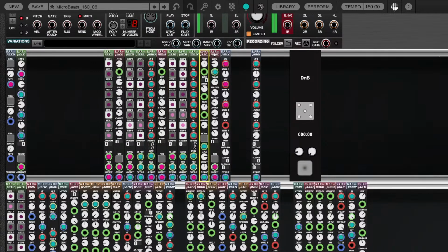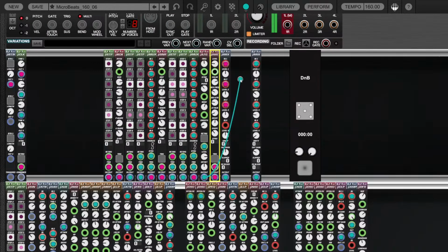Same goes for the hi-hat. Here, the hi-hat has two step sequencers that are also fed into a multiplexer. In this case it's an alternating pattern, so we turn this 8-step sequencer into a 16-step sequencer. And the hi-hat has the special thing applied to it that it has an LFO modulating its level, which adds some rhythm to the whole drum beat.